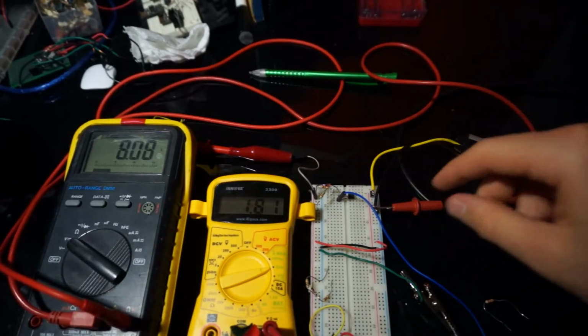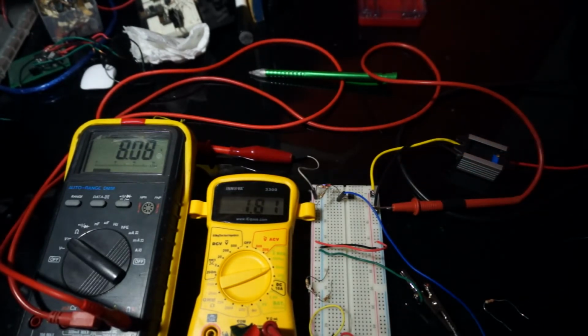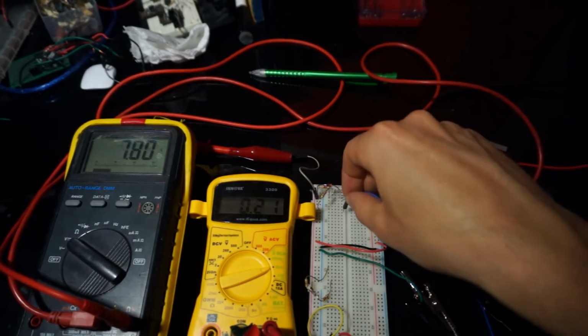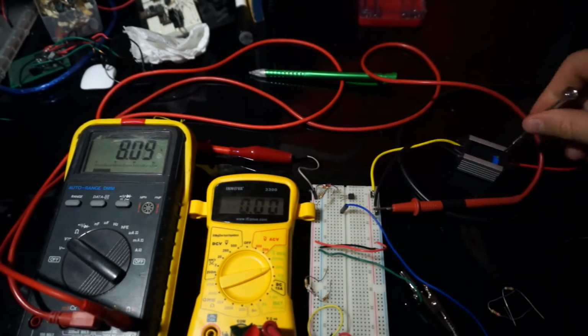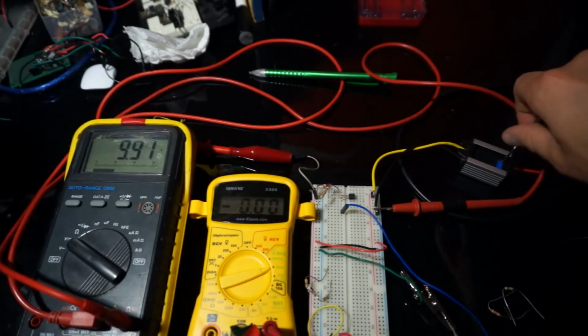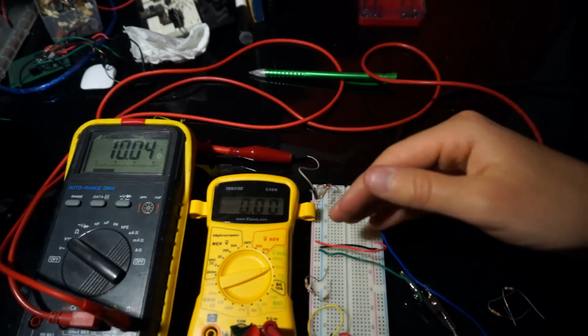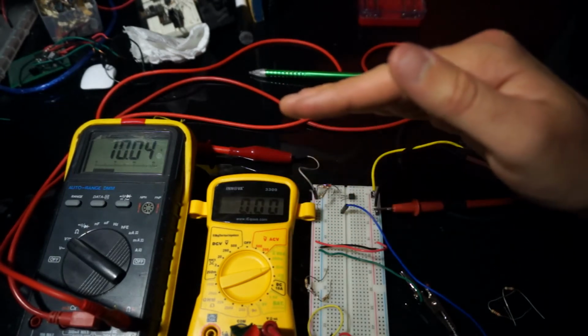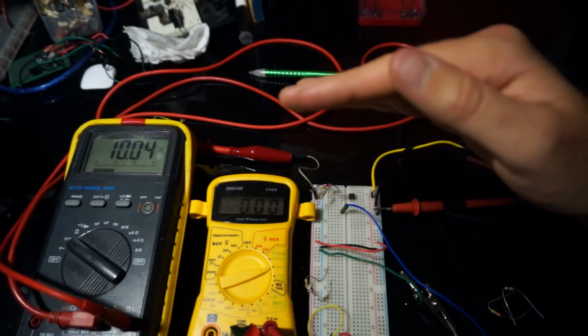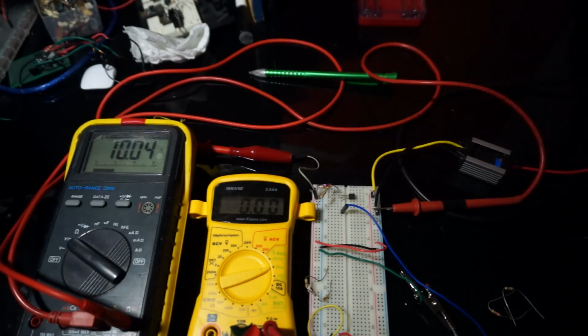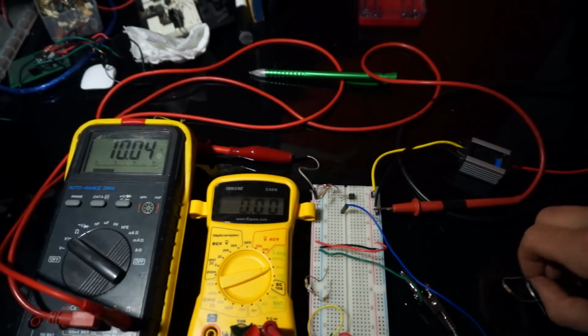But before we go there, I just want to also check the claim I made about the fact that the device under test resistance matters. So again, remember, if that resistance creeps too high, then it's going to push the collector voltage up towards the emitter, and it's going to take the transistor out of saturation.